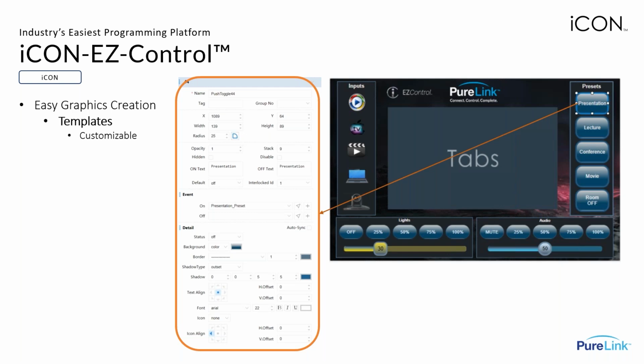or you can create your own statuses if the active, normal, or disabled, 3 options that come with every single button, aren't enough and you need more, alongside changing the text and having all of these be dependent on specific statuses of the devices. So we use this very often, for example, for the video transmission status of some of our AV over IP equipment. Since you can run AV over IP throughout the entire building, you are able to see on your touch panel the live status updates of every single decoder in your setup, all from the touch panel.